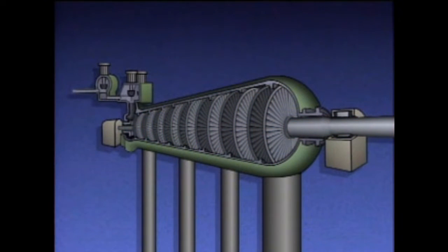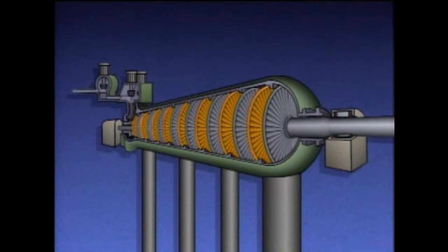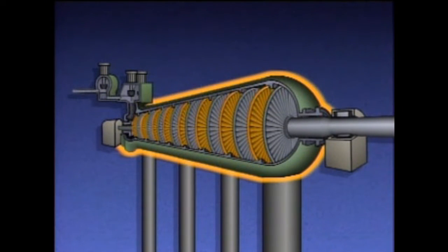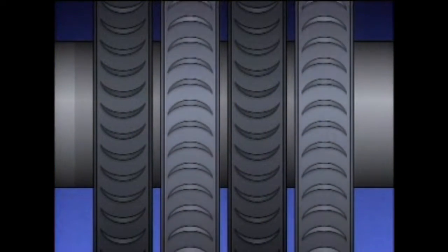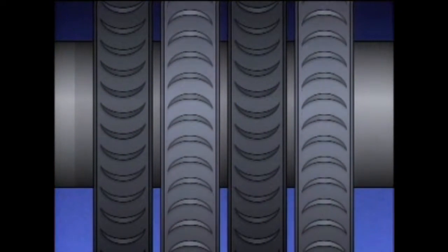Mounted to the turbine casing are diaphragms. They are positioned in the casing between the wheels. The casing and diaphragms are stationary parts of the turbine. Diaphragms are similar to wheels in that they are round hubs and they have blades. The diaphragm blades are sometimes referred to as nozzles. The distinction between diaphragms and wheels is the way they function during turbine operation. Diaphragms are stationary and their blades are fixed in position.